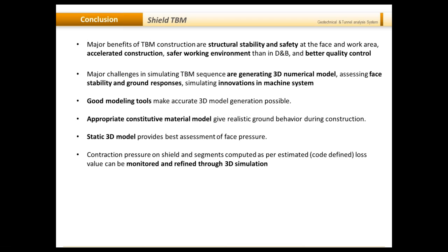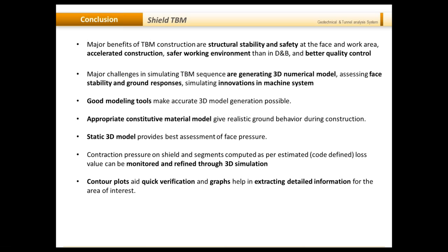So basically you can compute these values, apply them to your model, see the results. Like I said, you can make an assessment of a lower percentage, because then you will get more deformation later on due to the creep and shrinkage. So you can simulate, monitor and refine those values.